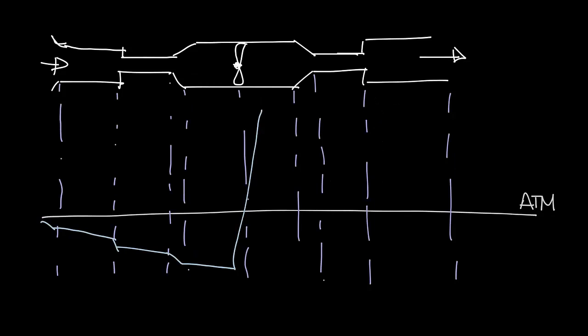pressure. Finishes the ductwork. Again, there's a little bit of loss, a loss at the transition, a little more straight duct. It hits this pretty hard expansion. There's more pressure loss, goes out, and then it hits the space and will return to atmospheric pressure somewhere after the end of, we'll say, the diffuser, which I didn't draw in.